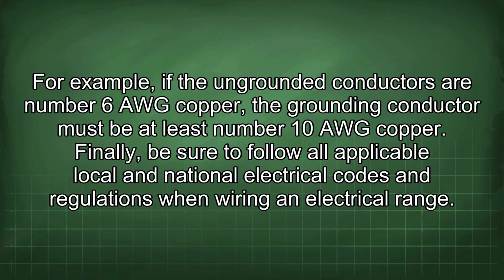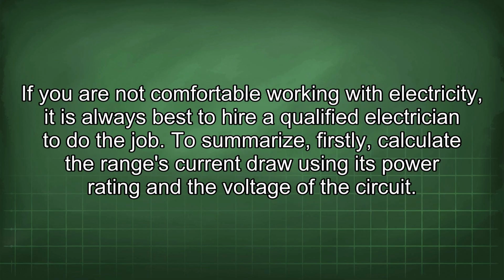Finally, be sure to follow all applicable local and national electrical codes and regulations when wiring an electrical range. If you are not comfortable working with electricity, it is always best to hire a qualified electrician to do the job. To summarize, firstly, calculate the range's current draw using its power rating and the voltage of the circuit.